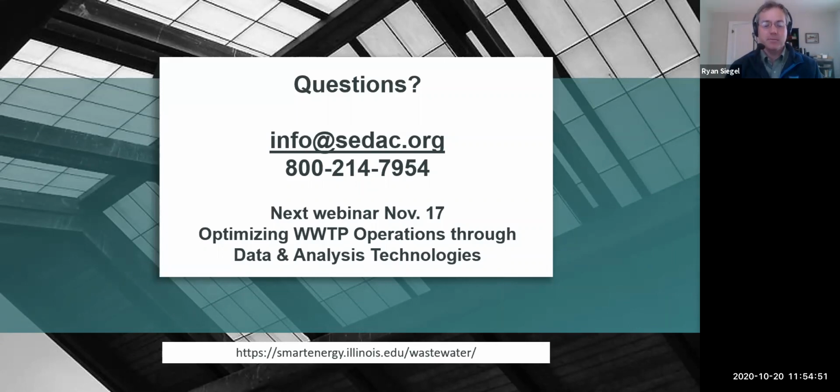So as Jackie kind of alluded to, for them, if they're able to save 20,000 kilowatt hours a month, that will save on their energy charge, but it may not save them on delivery charge because their delivery is going to be based on when that savings occurred. And if you can, rather than having peaks and valleys, if you can push those peaks down, you can really save on some of that delivery charge.